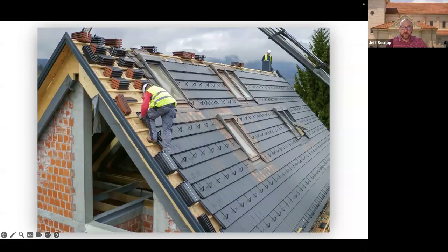Failure to do so, you can possibly damage your roof or damage your tiles, creating the opportunity for more moisture intrusion. And it typically takes a very highly trained contractor to achieve good results. Also noteworthy, we're going to have to over-engineer our roof structure. Slate being so heavy, you really need to consider the added structural support that's required for a slate roof.